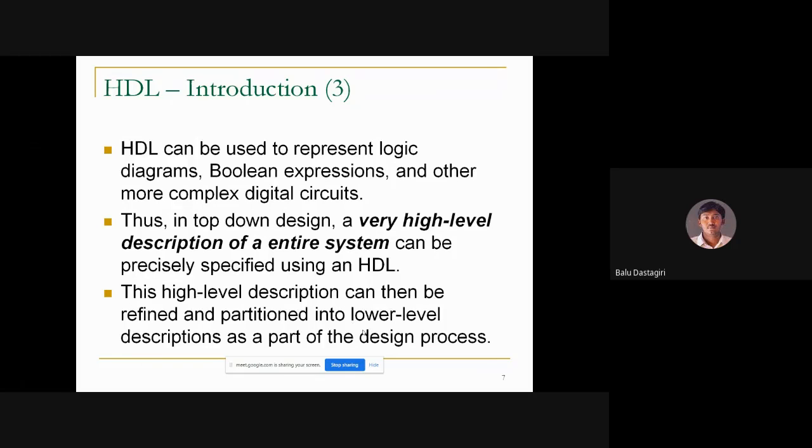Whatever full adder you have taken, as a designer we know that it is a full adder, but the person, computer, or software which simulates your program doesn't know what a full adder is. It is just a name. So again, we have to define the functionality of the full adder. You can define the functionality of the full adder directly, or by using half adders.